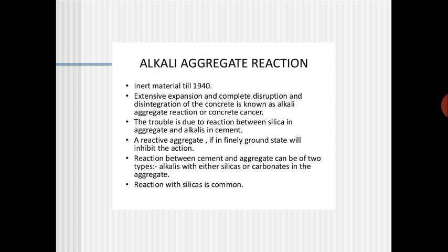Sometimes, to increase our strength, we add alkalis, sodium hydroxide, which is one alkali that we add in our normal concrete to increase the strength. In that case there are some chances that this alkali is going to react with the aggregates.